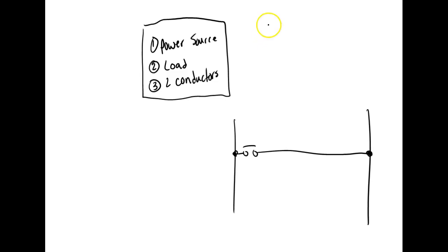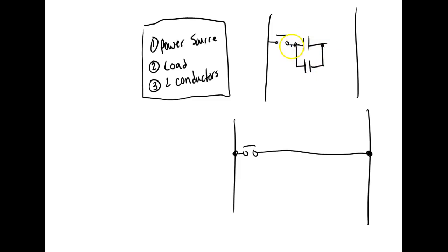If we don't have a dot, we're having to do things like this, where we had a line coming down, and this line right here had to come over and cross the line right there. And I know this is not connected because there's no dots. So that's why these dots are very important.